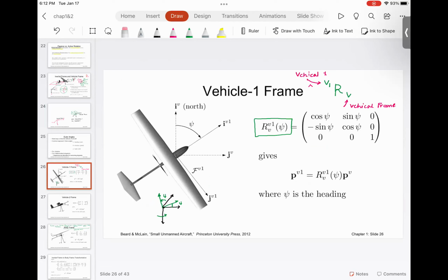Now, what we want to do is incorporate the respective rotations. The first rotation that we are looking at is the rotation about yaw. And that rotation, if you remember from robotics 1, is given as cosine theta, minus sine theta, sine theta, cosine theta, and you have 1.